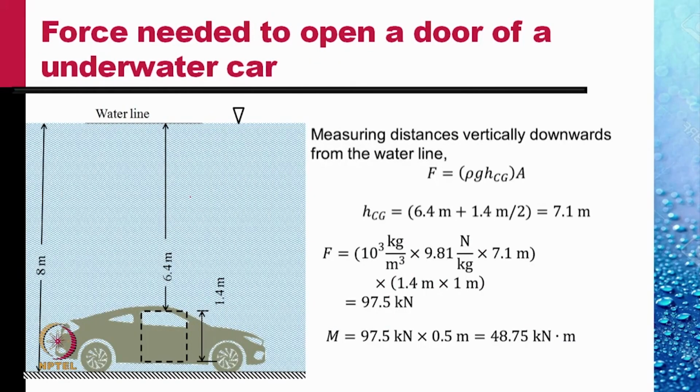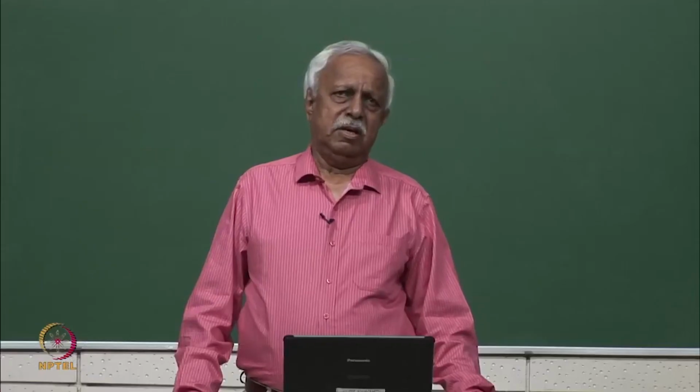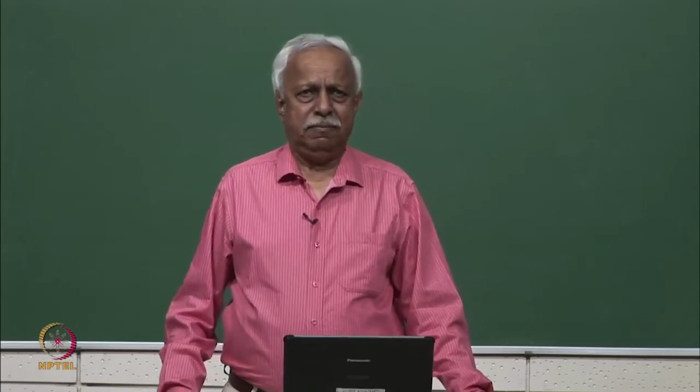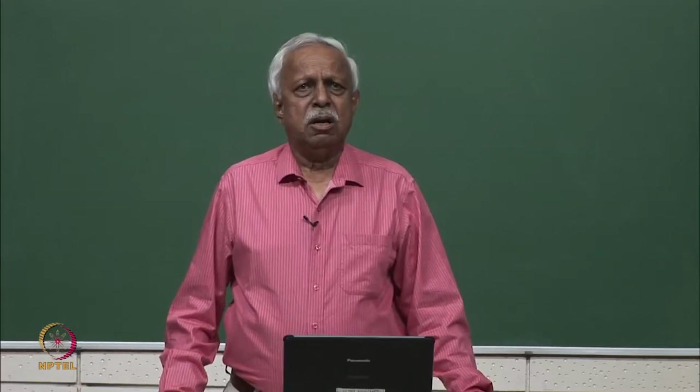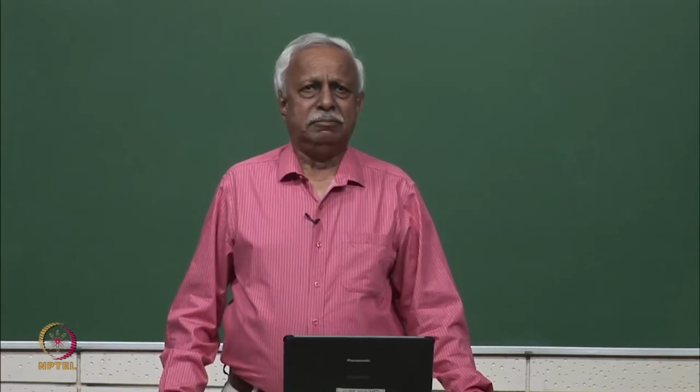Let us now do one more example, where we find the force needed to open the door of an underwater car. Suppose a driver with a car takes a plunge in water and the car comes to rest at the floor of the pond 8 meters below the water line. The dimensions of the car are given. If the driver wants to open the door of the car, shown in broken lines here, what force would he need to apply?